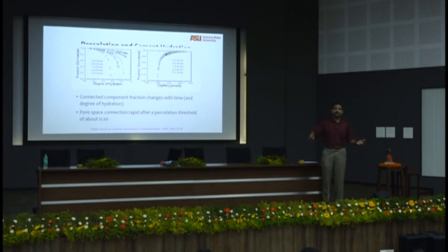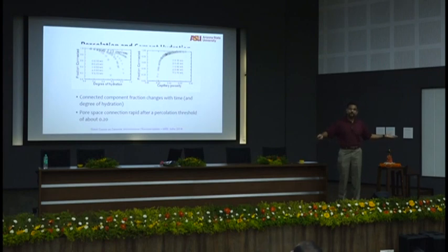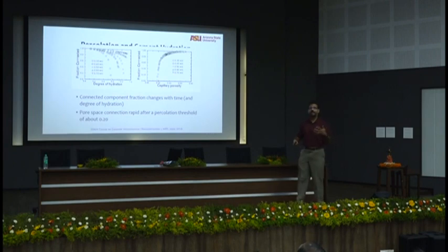Yeah, but out of that 20% fly ash, how much is reacting? Now, this is for a cement which can hydrate. How much of a fly ash can hydrate in a standard cement system? Very, very little. So if you're putting in fly ash, you get some initial benefits because of the density difference in packing, but then after that you lose it, right? So if you use a fly ash and then use a higher water cement ratio, you are in the same situation still. So the control has to be in the microstructure,